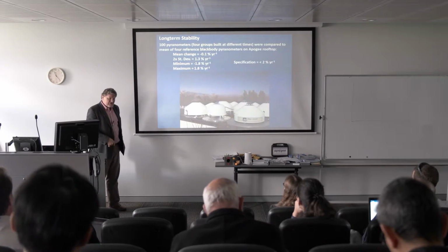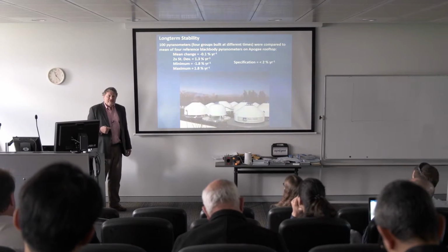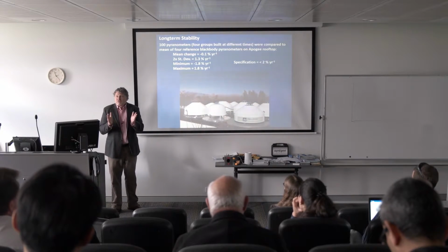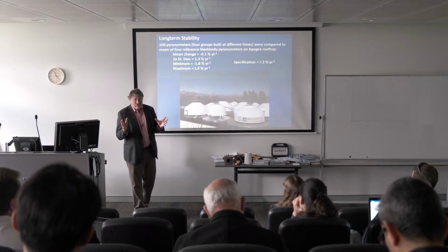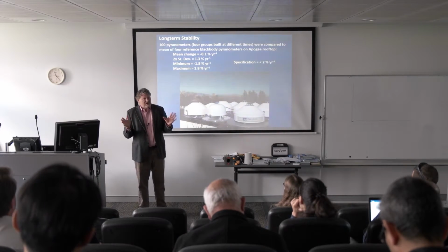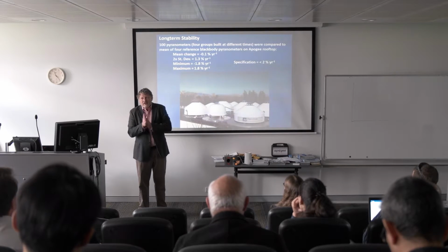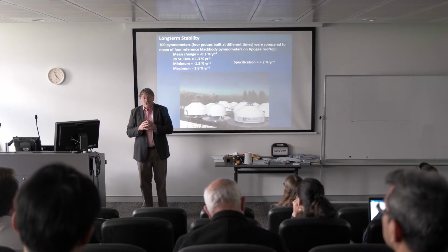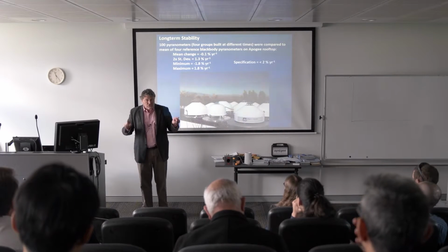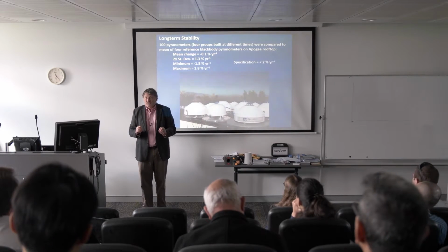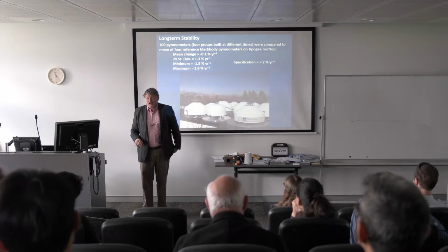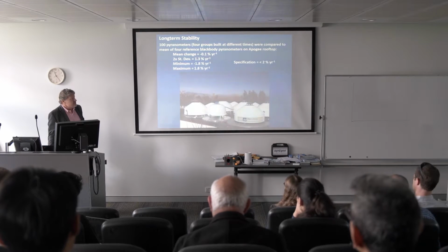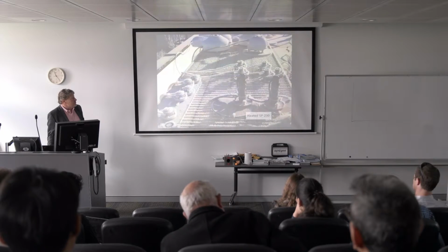And again, I talked about this accelerated aging before, but to really be sure you've got quality instruments, you need to check long-term stability. It's one of the troubles with new instruments. Everybody gets excited with new instruments. How much did the manufacturer test those for long-term stability? You can't put them in an environment for 10 years. You're depriving people of that new technology, but you can run accelerated aging tests to try and make them fail to get better confidence that they're going to work in a range of environments. The tropics and the cold places, warm places, that's a critical thing with research-grade instruments.